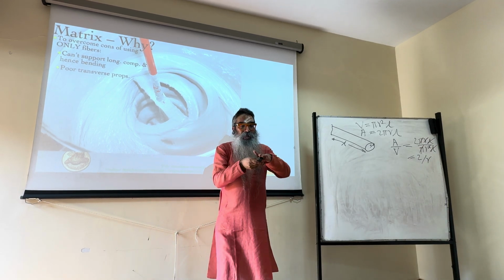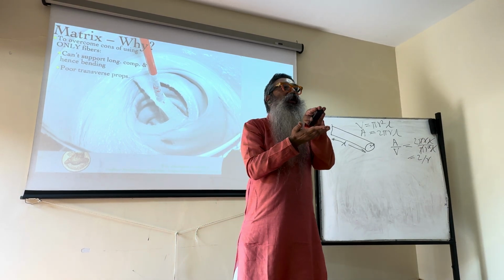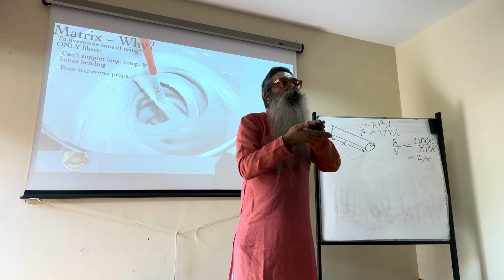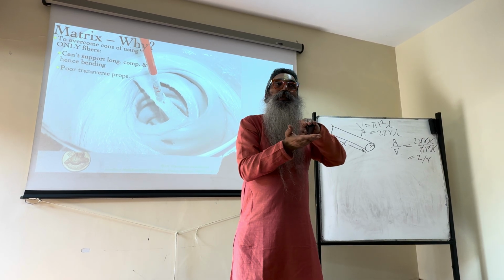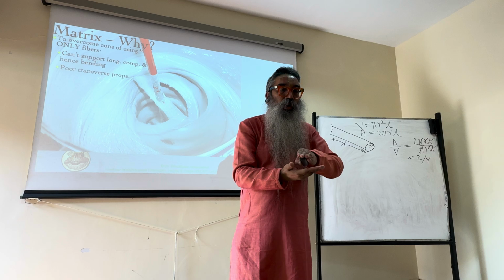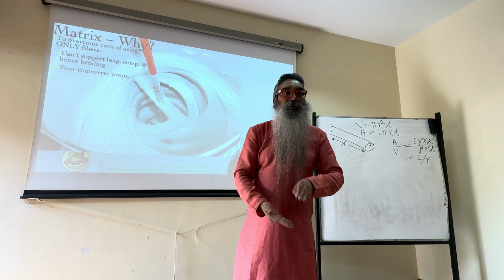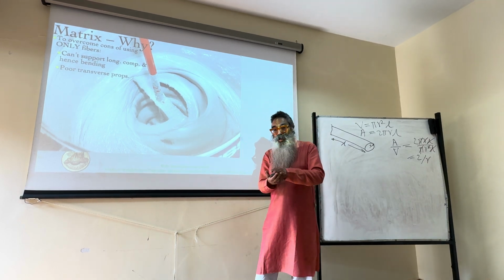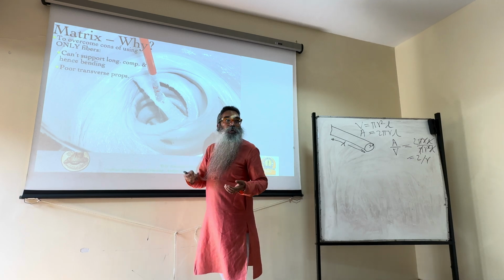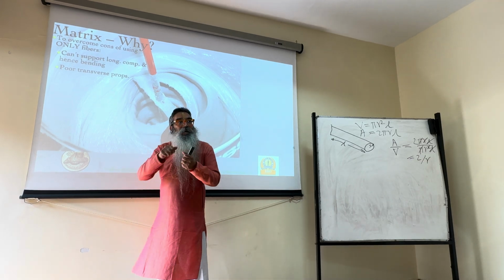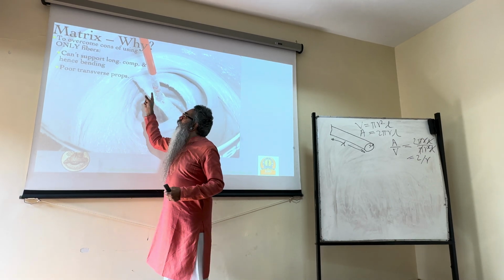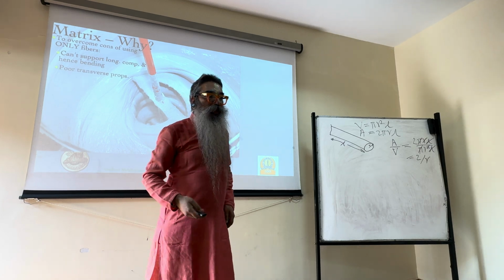Of course, a better way to handle that is to have multiple layers, a laminated structure in which you go for cross plies or plies in all the load dominated directions in different phases of flight, so that you can have a laminate which is well designed to take loads in all directions. But if you have fibers alone, obviously that cannot be done because it has very poor transverse properties.